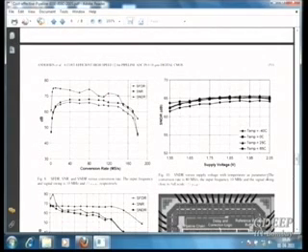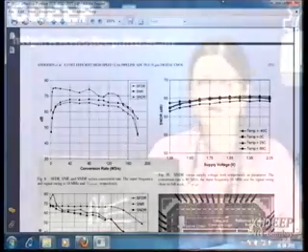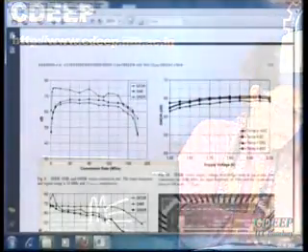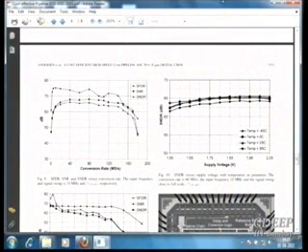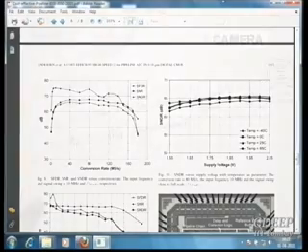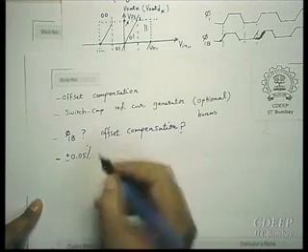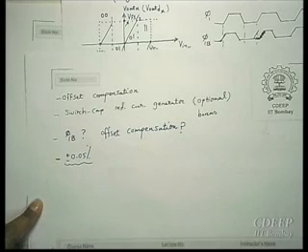Okay, so see, regarding what you need to consider for your non-idealities. Of course, Opamp is not an ideal component, therefore automatically you will get all non-idealities associated with Opamp, for example, finite gain. But one thing you need to see is how much offset or mismatch we should consider. So the amount of mismatch that you can consider will be 0.05%, okay, as an initial value.